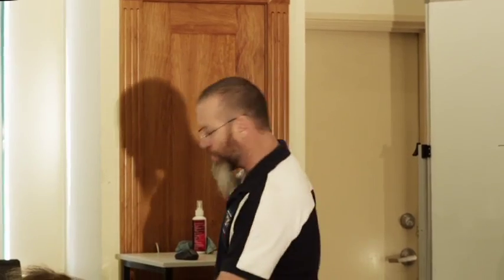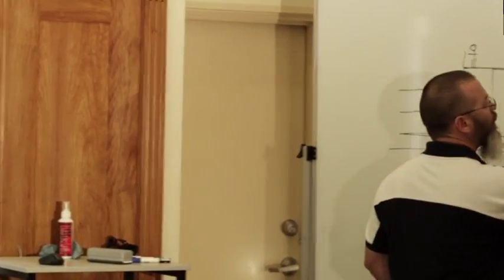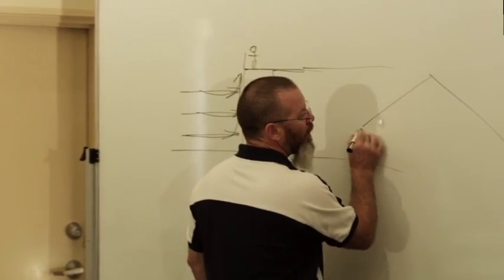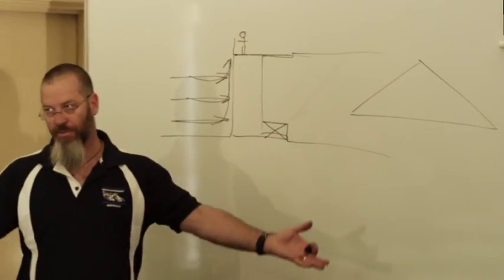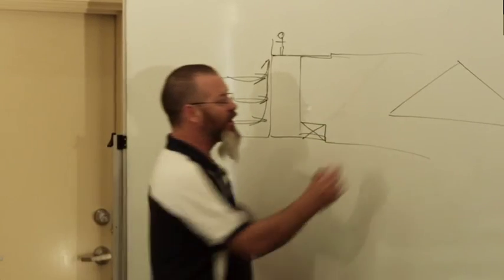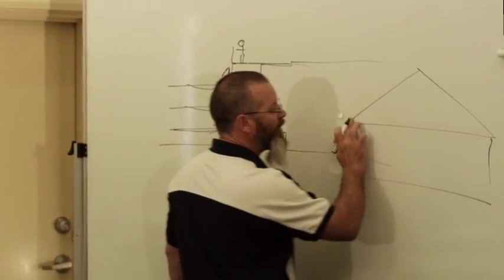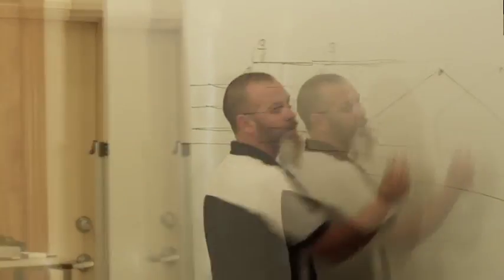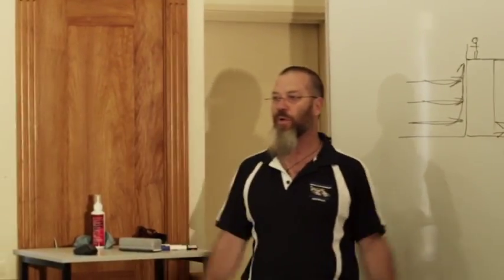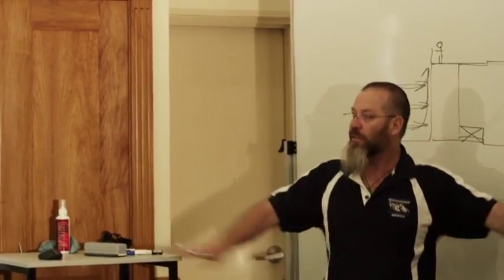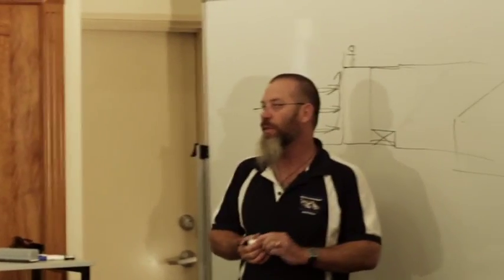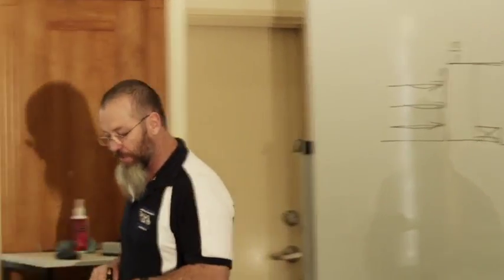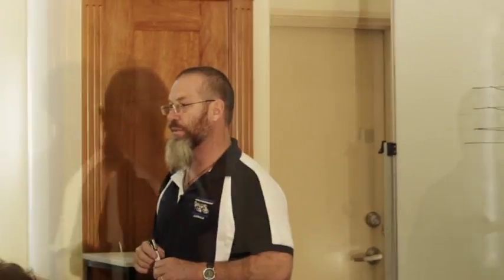A coupled roof is a stick roof. A non-coupled roof, that's a coupled roof, or a truss roof, that's a coupled roof. A non-coupled roof is where you have a supported ridge which is supported either end. So there's nothing in the centre of that to stop that roof from sliding out. That's non-coupled. If it was a coupled roof or a stick roof, you'd go straight there where it says coupled roof, and all you've got to do is put 2 skew nails in there. 2 3-inch skew nails. That's all you need to hold the roof down.